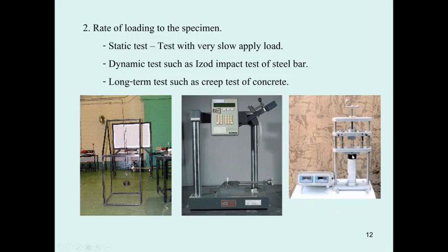When the concrete is subject to long-term load applied on it, the water that is in the air voids will move out of the concrete, and then the concrete is going to have some permanent deformation from the long-term application of the force. So this creep is important when you design pre-stressed concrete structural members such as the beam or the column.